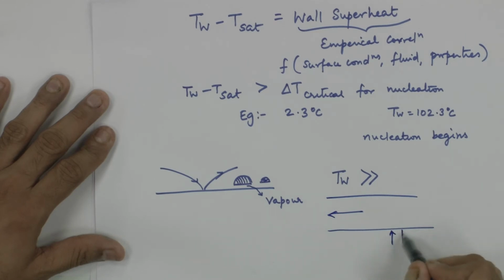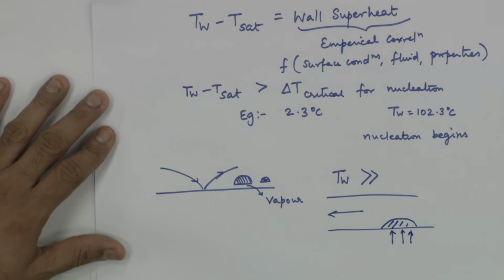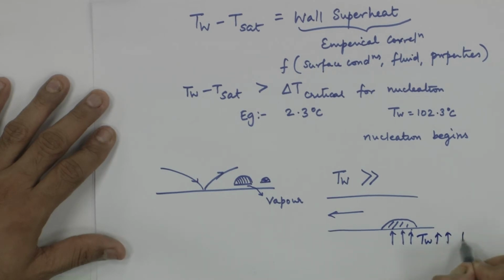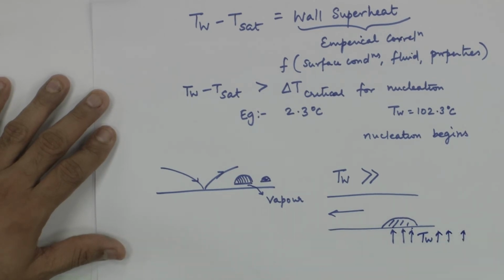Local hotspot means where there is some kind of flow maldistribution, and you come up to a surface where there is no flow in this path, and you are supplying heat, there is no sink for the heat, and this wall temperature here, T wall, will start to rise significantly, and because T wall starts to rise, you would lose the structural integrity of the surface.